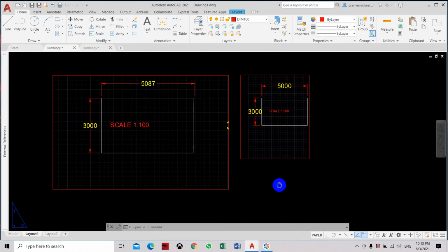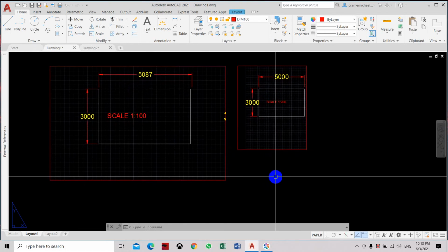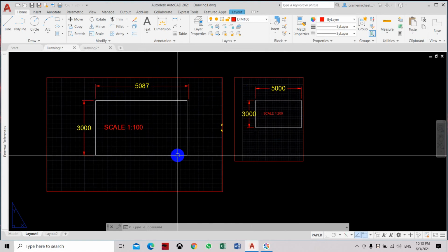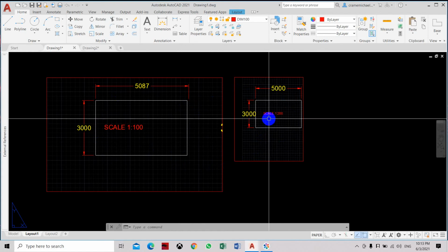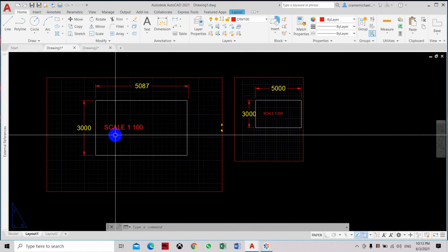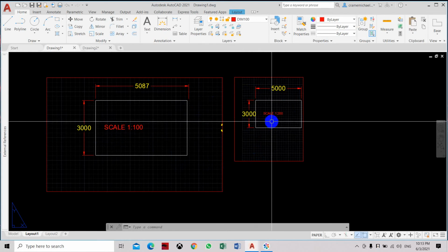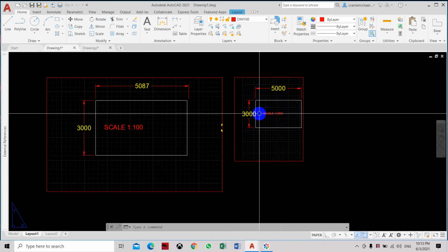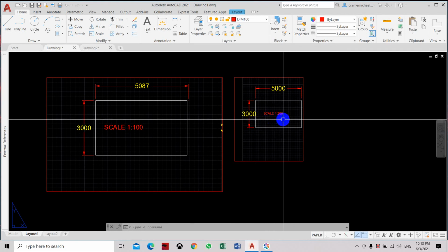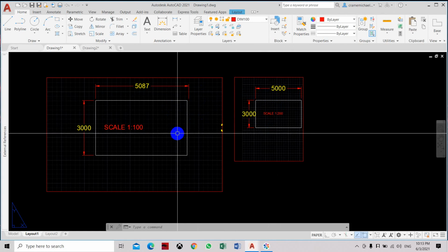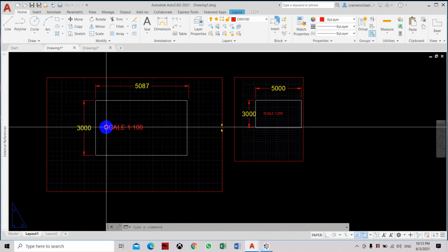But in the drawing, in the paper space, when you're going to plot the drawing, once you scale this drawing into the correct scale, if you have the same dimension style, once you scale it into 1:200, it will be smaller in size. So basically, the correct adjustment shall be done on the dimension style, or you can create 3 dimension styles, which is correct for each scale preference.